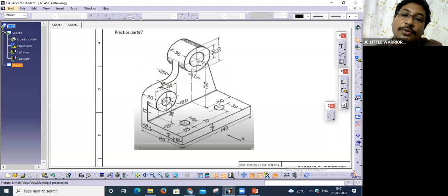If you check here, this is 12 mm, from this cylinder front face to the wall. And the thickness of the wall is 12 mm. That is 12 plus 12, 24 mm, the distance of this rear face. So we are creating this rear profile, because the dimensions are given for the rear profile. Have you seen that?